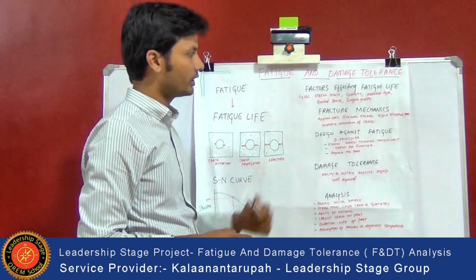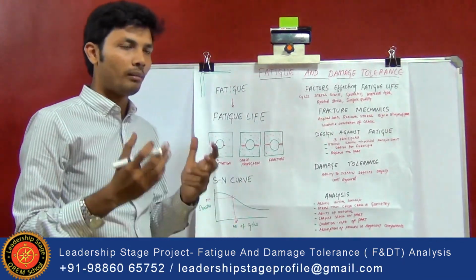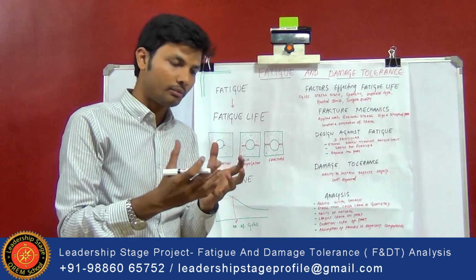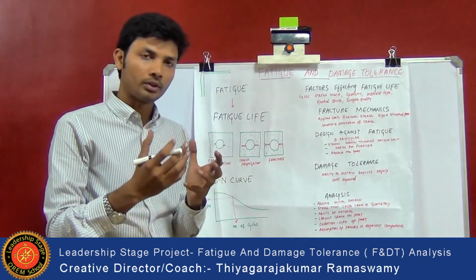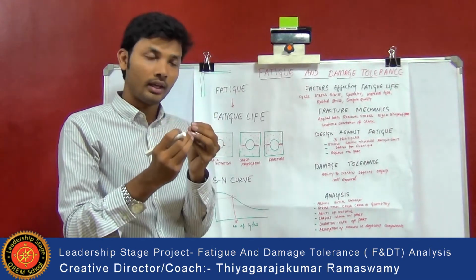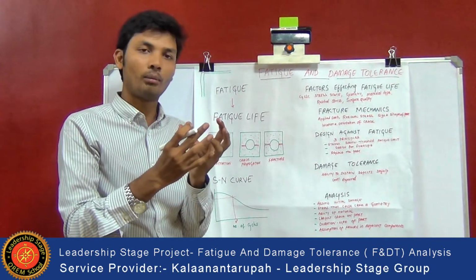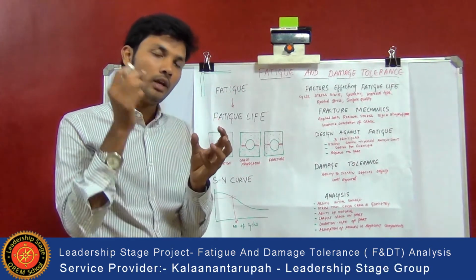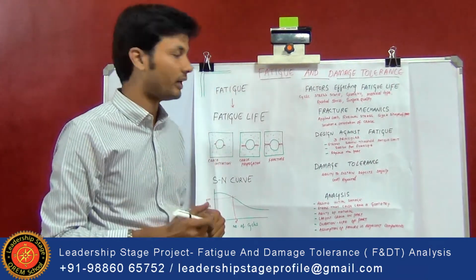And the residual stress. Residual stress is nothing but, while manufacturing the component, for a casting process or any process, there is a chance of having air bubbles or porosity in the component because of the manufacturing process. Even that will reduce the fatigue life.